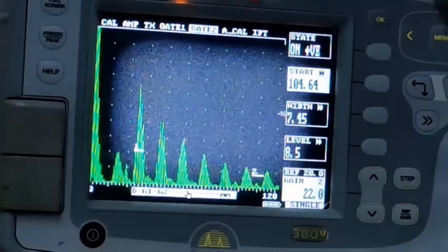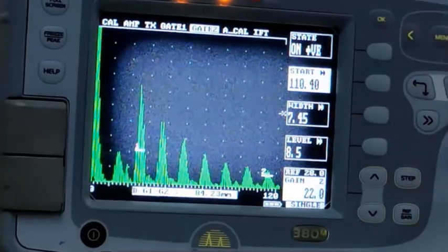Okay, so we can change the mode from G1 minus G2 to only depth, and switch off gate 2 and read only gate 1. That will tell us whether the depth or the distance is properly coming onto the transducer and being displayed here correctly or not. So let us go ahead and do that.